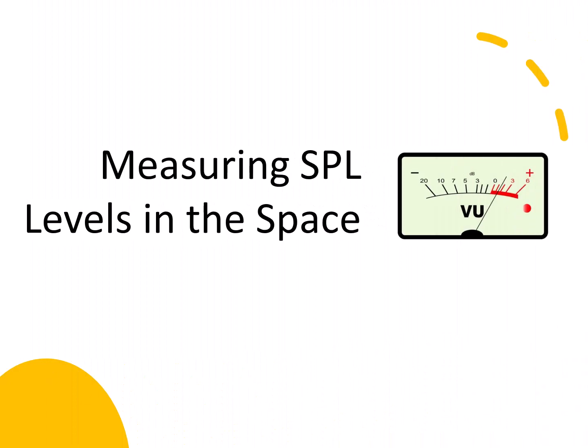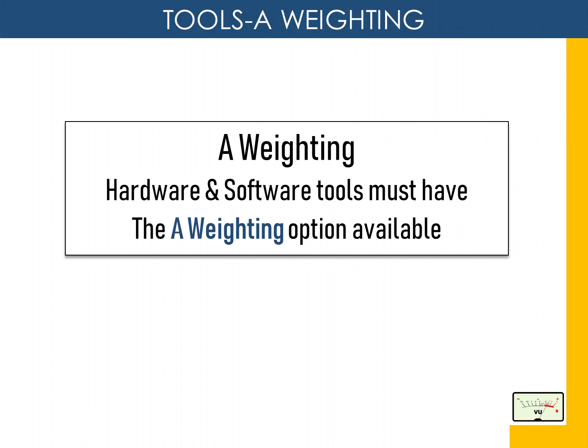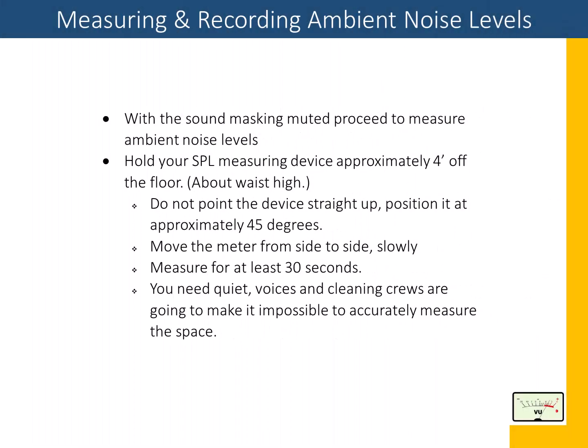Okay, let's start measuring sound pressure levels. Remember, whichever tool you select for measuring the sound pressure levels, that tool must have A weighting available. You may recall that A weighting most closely mimics the way that human beings hear. Just a few moments ago, using System Manager, you brought the sound masking levels down to their off position.